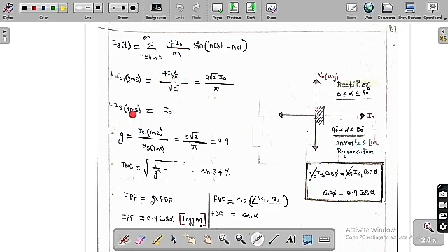And if you want to find the overall source current RMS value, it is equal to I naught. The overall source current RMS value is equal to I naught, whereas g is called the distortion factor. It is the ratio of the RMS value of the fundamental component current to the overall RMS value. We know the values of IS1 RMS and IS RMS, so doing the division we get 2 into root 2 by pi, which is 0.9. So 0.9 is the distortion factor.